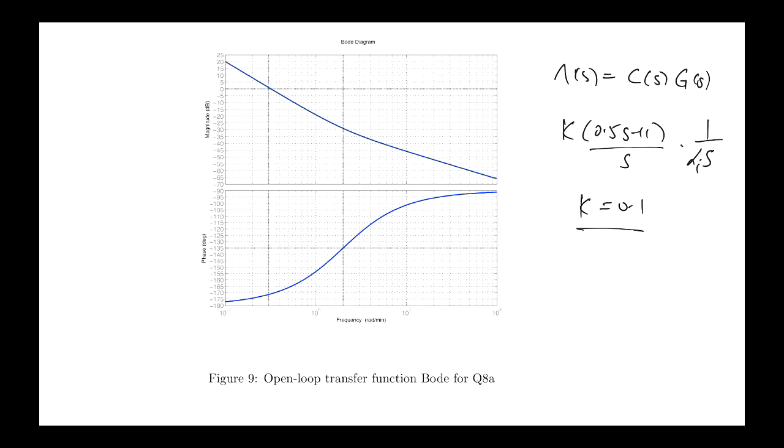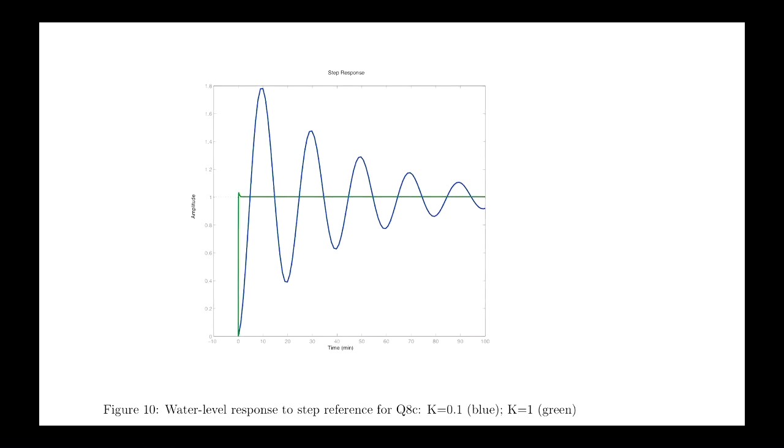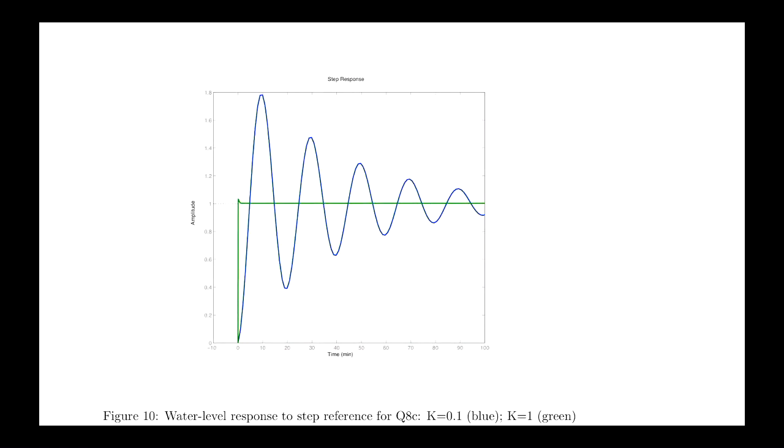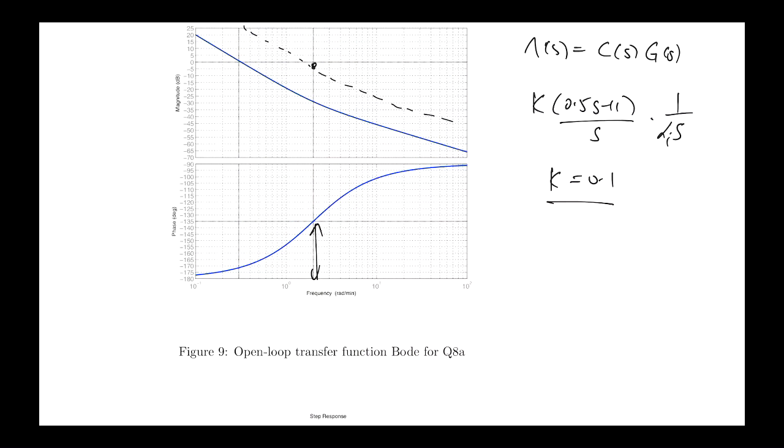Okay? And by increasing the phase margin to 45 degrees, by increasing the gain, which will just shift everything in the gain plot up by the same amount across all frequencies, well, if we do it right, we can make the crossover frequency there where the phase is minus 135. Okay, and if you look at the time response for different situations, you get this sort of time response, right? So this is when you've got to remember that this is when k is equal to 0.1.